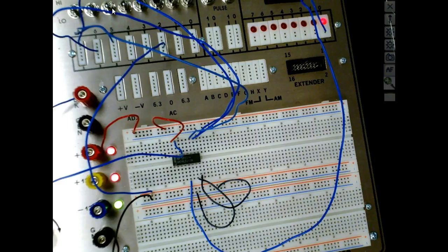Are you okay? The 74154 is a dual purpose chip. It can be used as a decoder, or it can be used as a demultiplexer. If used as a decoder, the enable inputs are tied low, and the 4-bit binary inputs, A0 through A3, or select ABC, right? You understand that?